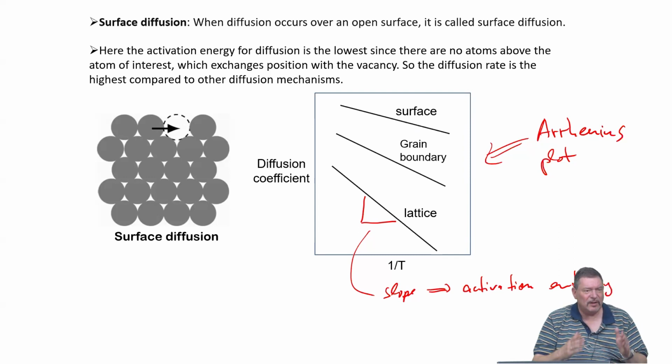Yeah, but let's say your diffusion zone, let's put it like this. In a scanning electron microscope, you can only, in cross-section maybe, get the average concentration of a certain element. So you can measure diffusion profiles. But the resolution is not sufficient to look at individual defects. So you will not see diffusion along a grain boundary. You will not see diffusion along a dislocation core.